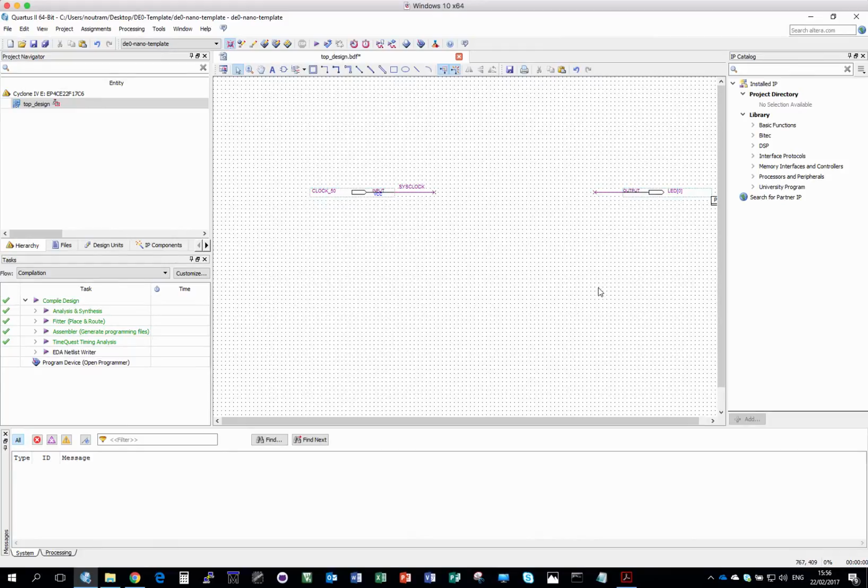So I want to divide this clock, 50 megs, pretty fast. I want to get it down to something for demonstration purposes. Now we could write some VHDL to do clock division, but actually this FPGA has at least one phase locked loop, which is an analog or analog digital device with circuitry that can scale your clock in ways that would be very hard to achieve yourself. Now I believe there are 4 of those on the chip. I'm only going to use 1.